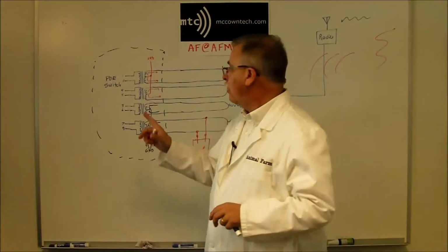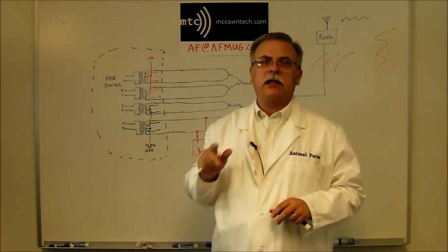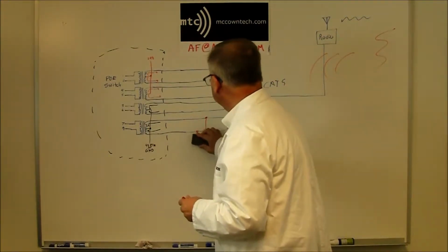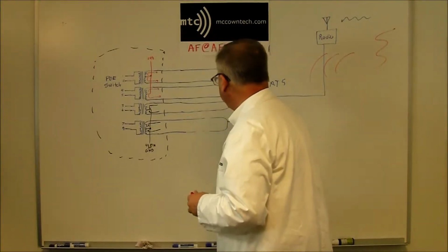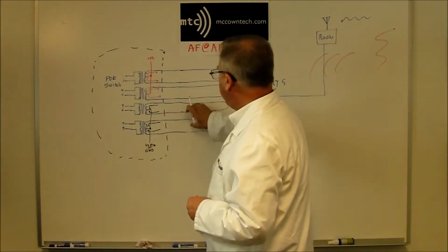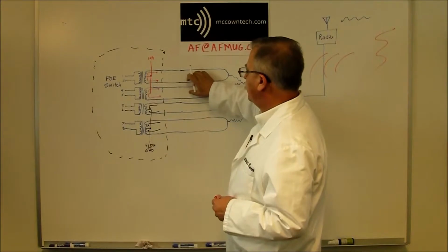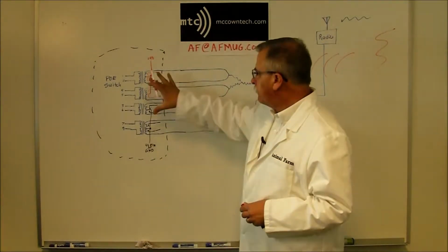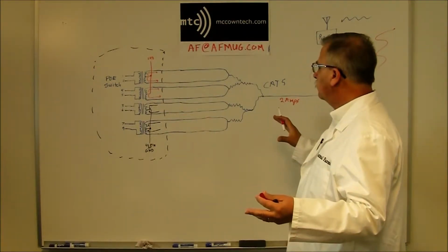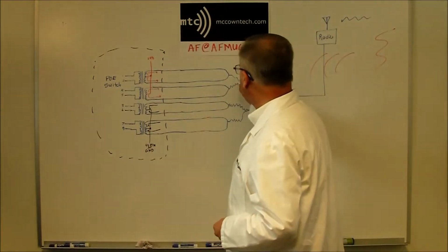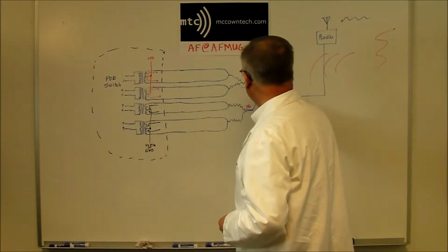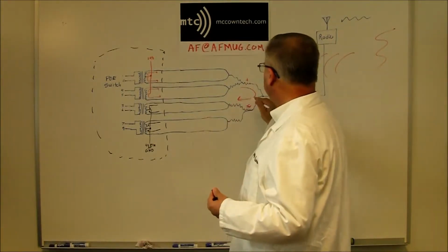Any single one of those will wipe out a PoE device that doesn't like to be shorted out on its output. Typically these PoE devices can put out 1 to 2 amps aggregate total. So we're talking about all 8 wires, 2 complete circuits. If this device has a limit of say 2 amps total, this is the positive circuit here, and this is the negative circuit. So you've got this round trip loop current that's 2 amps.